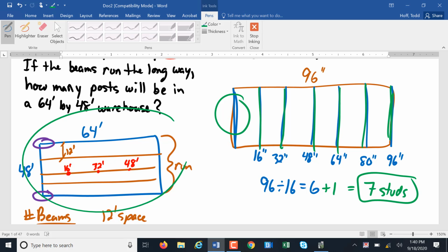You know how that works, don't you? Yeah, the 6 is a 6/8. A number 4 is a 1/2 inch, 4/8, because most of what we did was number 4. Yep. Well, for stuff that's vertical, if you have any walls, those usually use a number 6 bar.